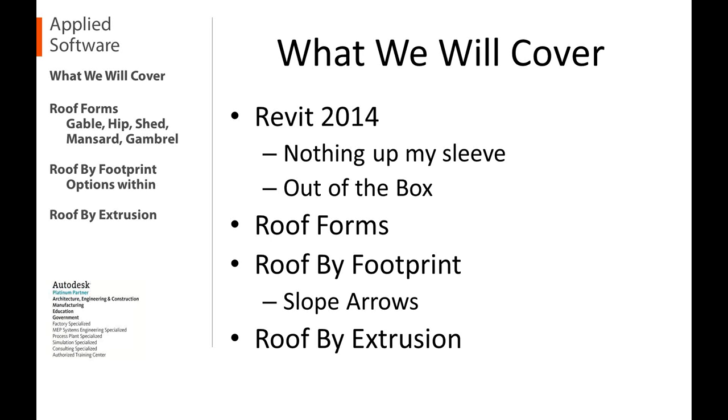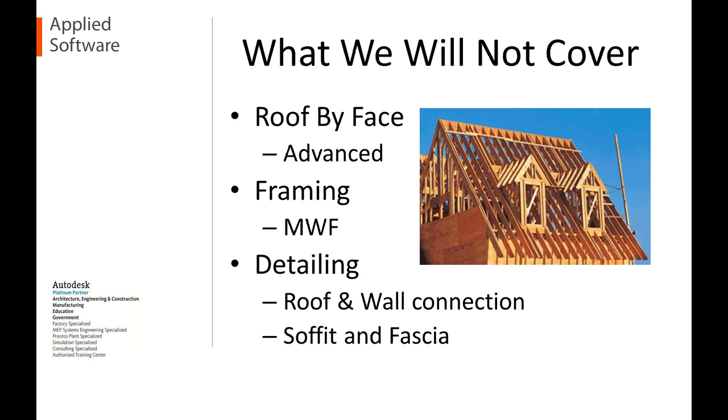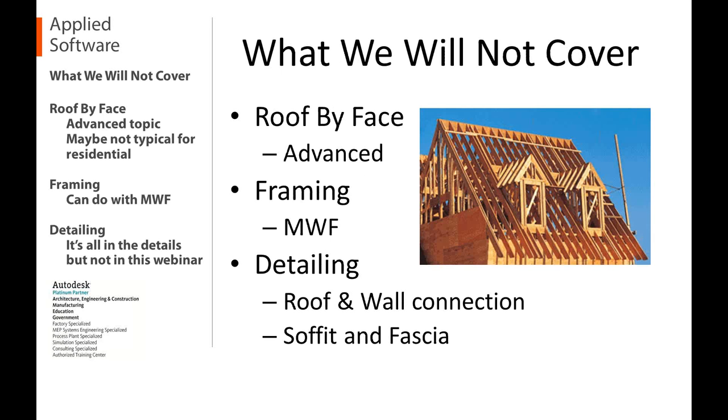We will look at some specific roof forms that we'll create. Again, we'll use the roof by footprint, use the slope arrow, and I'll show you roof by extrusion. What we won't cover is the roof by face, which is an advanced topic. I need to first show people how to use massing inside of Revit before we can start placing a roof on a mass.